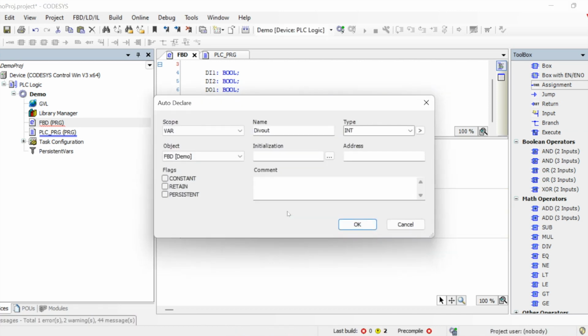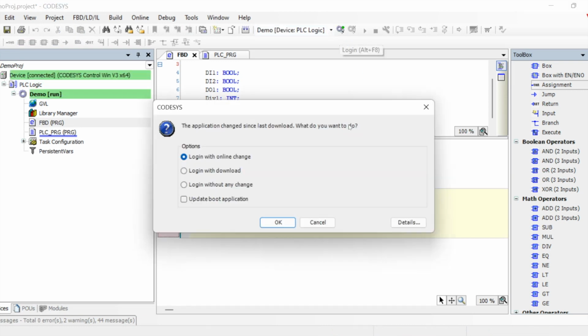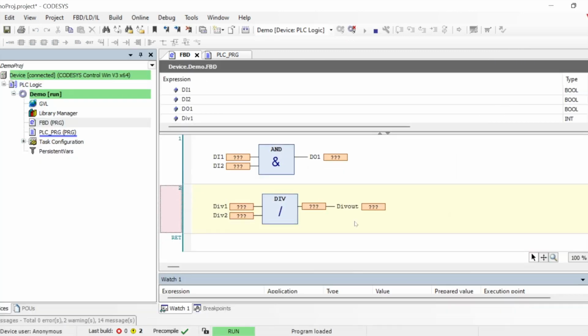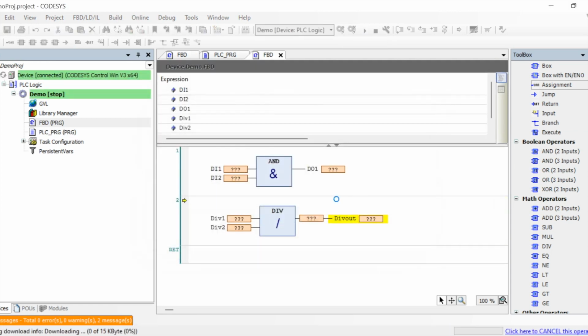Now when we are working with any maths block, I'm just trying to show how exactly it works and what things we need to take care of when defining these blocks. You can see that my initial value is 0 and we go into division, so it brings the PLC into an exception, a program load exception, correct? We need to be careful when utilizing mathematical blocks or any blocks where we can think it can bring exceptions. If exception handling is not taken care of by us, it can lead to the program load exception, because of 0 divided by 0. That is a very basic point.